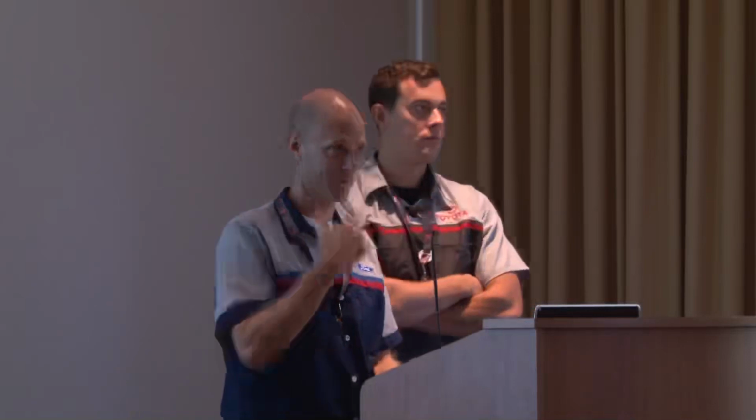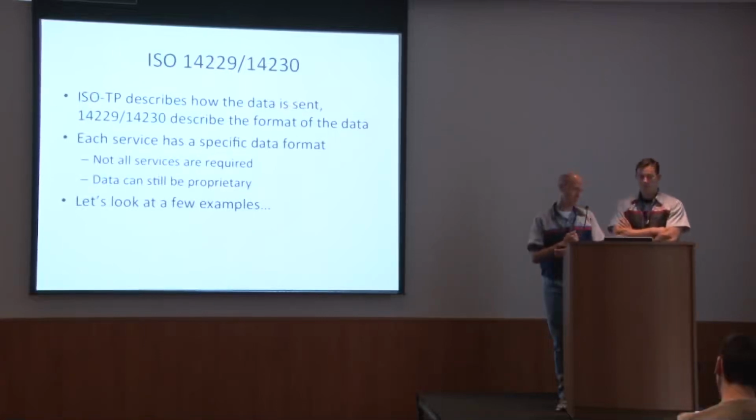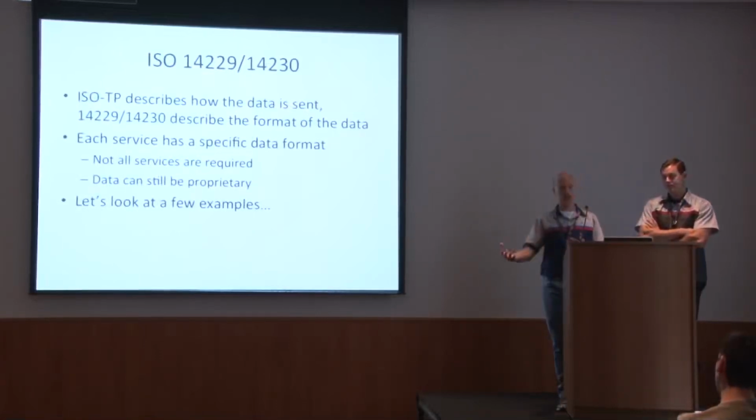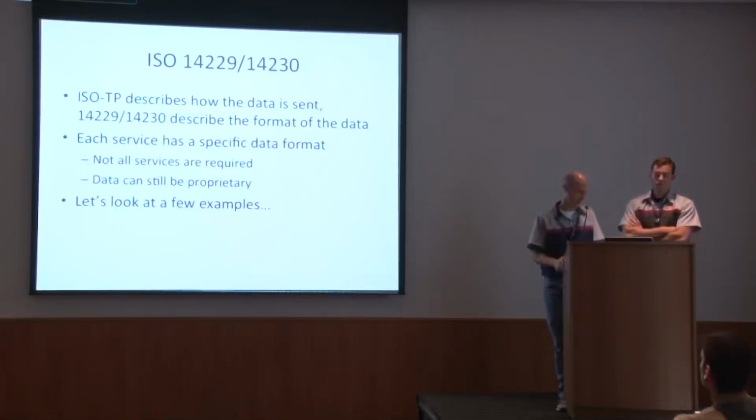So that just says how to send a lot of data, but it doesn't specify what data to send. You can do anything, but there is a standard, ISO 14229 and 14230, that specifies the format of the data, and both of our cars sort of followed it at times. They specify different services that you can talk to. This is especially for diagnostic packets.